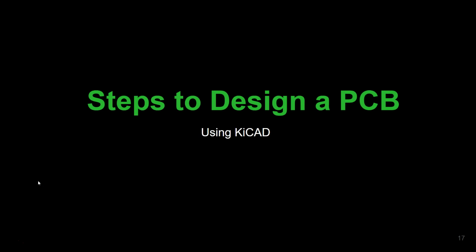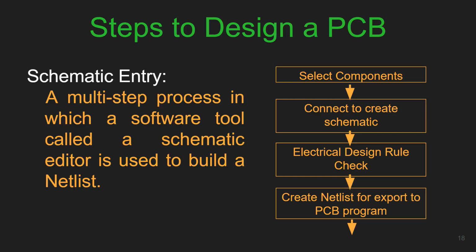Steps to design a PCB. So in our program, we'll be using KiCad software to design a PCB, and using the KiCad software, there are different steps involved in creating the PCB, and we are going to study those steps. So the first is the schematic entry, and under that we have a selection of the components, connect to create schematic, electrical design rule check, netlist creation. All these four steps come under schematic entry.